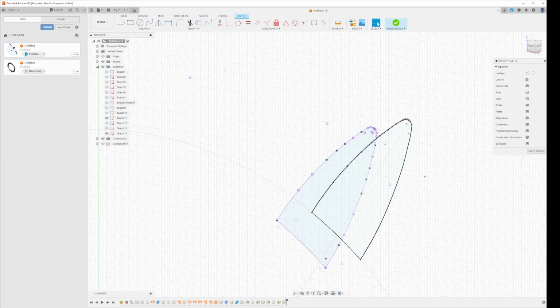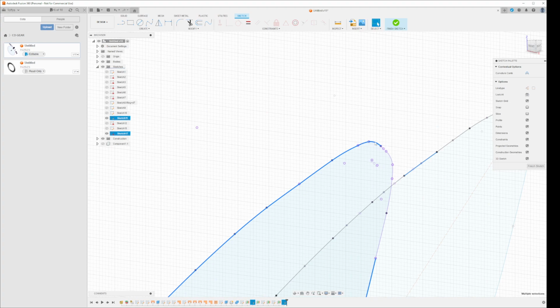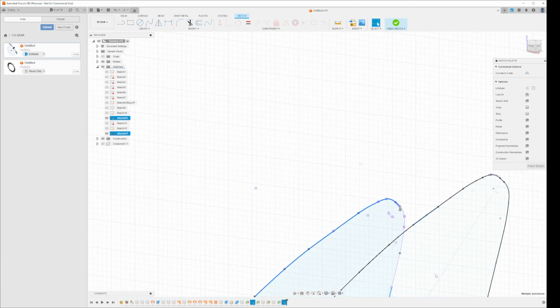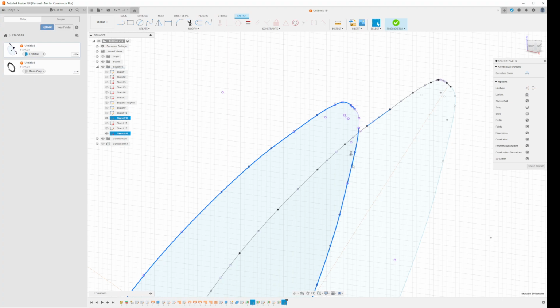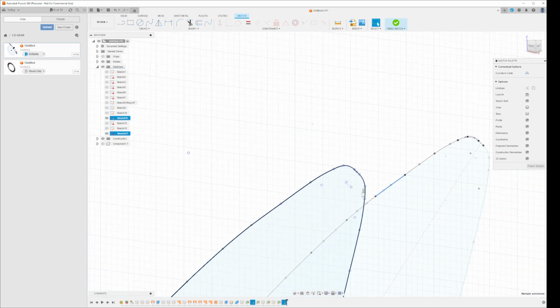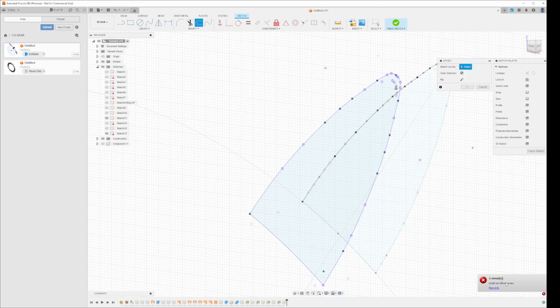Now I want to offset this a little bit further in. So let's just multi-select everything again, just the way we did with the double click. And here, here, and here. I'll start from the bottom again here. Hold Control, double click, and double click, and double click. And now you see that's clicked. Okay. So now I want to try and offset that to be a little bit smaller because I want to project it. So O for offset, and now you see could not find offset curves.